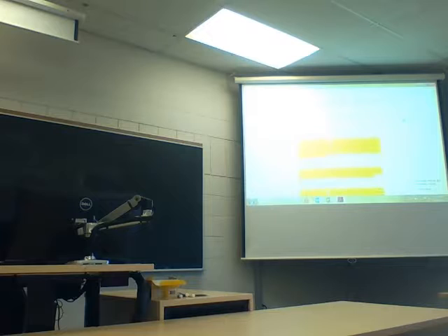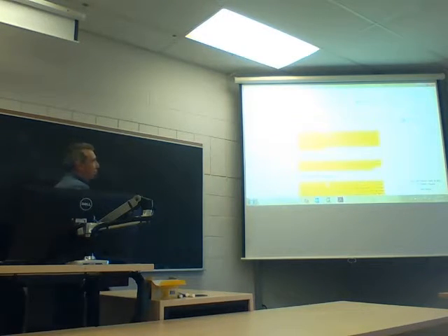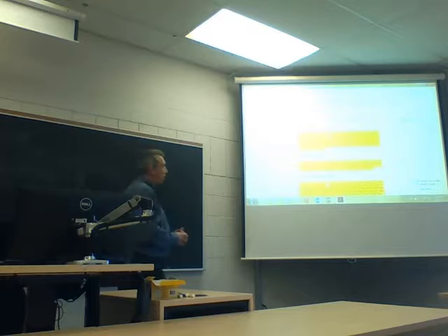Air compressor, I'm really hoping you guys know what an air compressor is. The one they're talking about makes continuous pulse-free air. It's a two-stage positive displacement, fluid lubricated type. It's a lobe. The only major moving parts are the two lobes. So that's what a positive displacement lobe is. Air fluid separator. Just take a guess what that does.